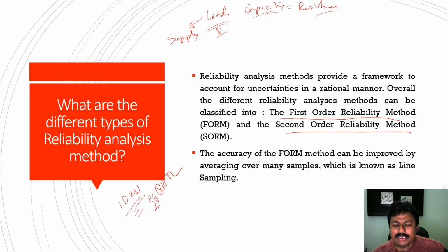This rho is known as density of water or the fluid. g is acceleration due to gravity, and this Q is your discharge, this H is your head, and this eta is the efficiency of the turbine and generator, by which the kinetic energy of the water is rotating to generate power. So here I am taking how much discharge is required to generate this load. Suppose my demand is 10 kilowatt, so how much discharge is required to generate this demand, right?